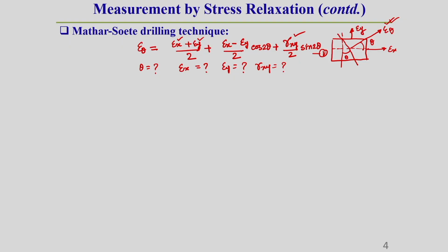Now, last lecture I discussed that once a body is subjected to a plane stress condition, that means in a 2-dimensional case, if we know epsilon x, epsilon y, and the shear strain, and if we know the Poisson's ratio mu and the Young's modulus E, then we can easily find out sigma x.